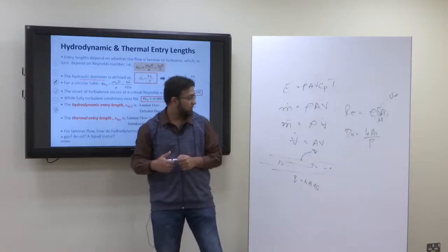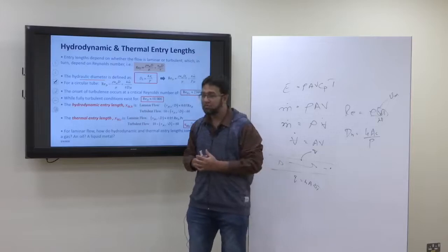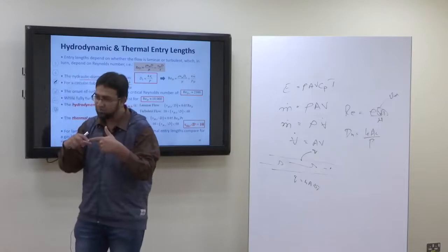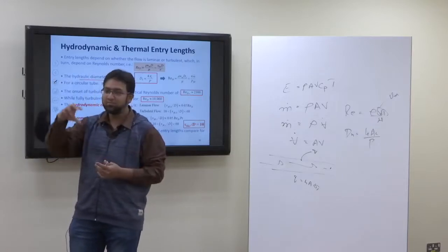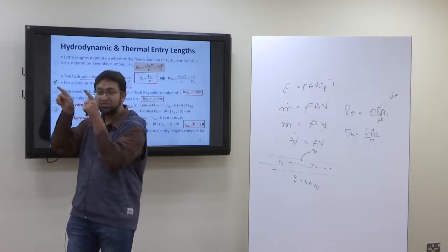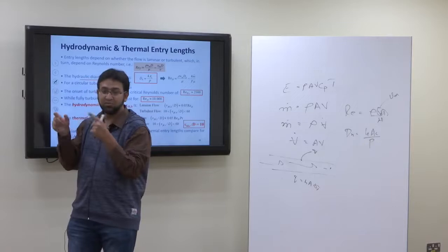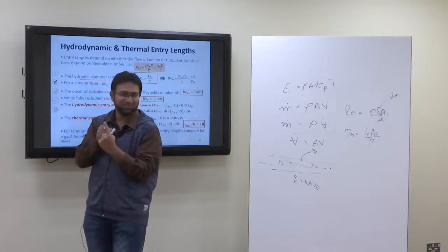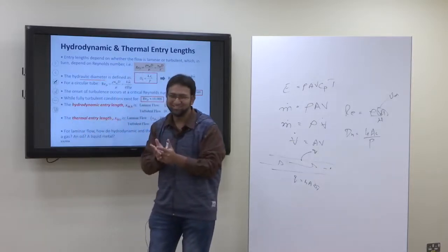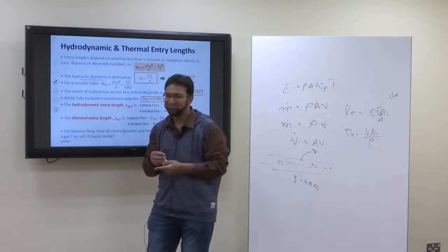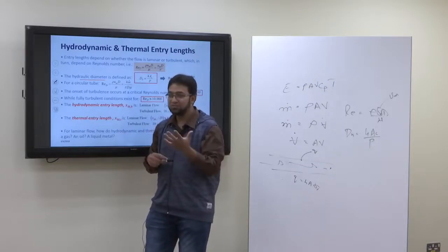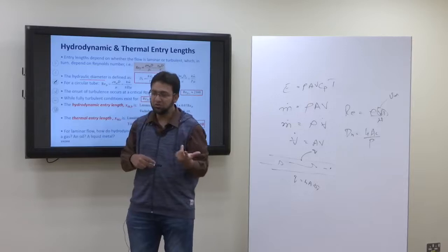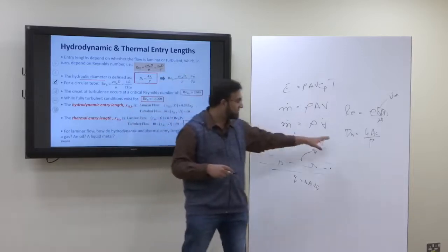Now, the thing is that we are considering internal flow. It's possible that the internal flow is within a pipe. The pipe may be circular, or it may be rectangular. Maybe the pipe is triangular, maybe octagonal or hexagonal. Sometimes that happens. So if the pipe is not specifically a circle, then what should be the D? So we found it as the hydraulic diameter.